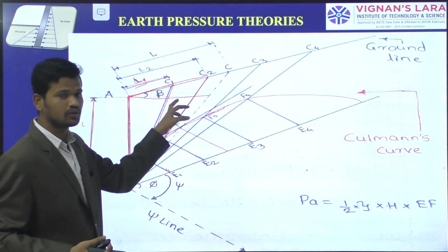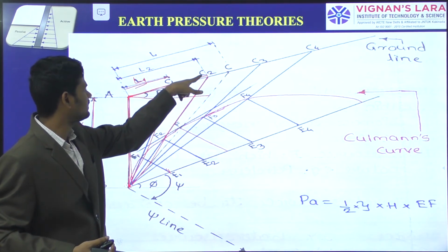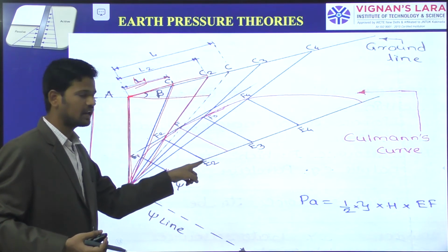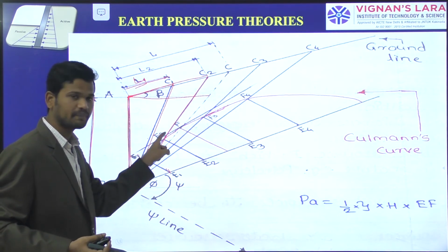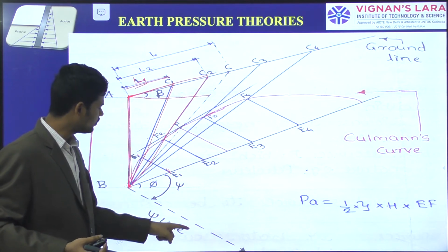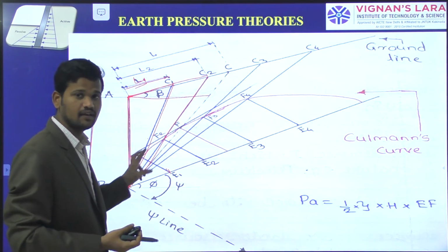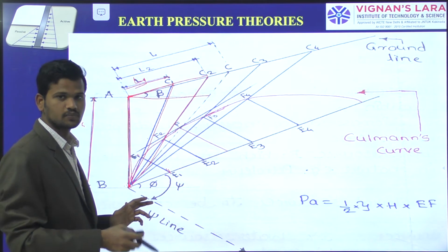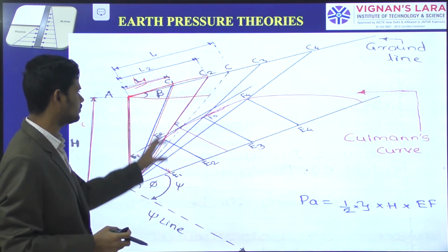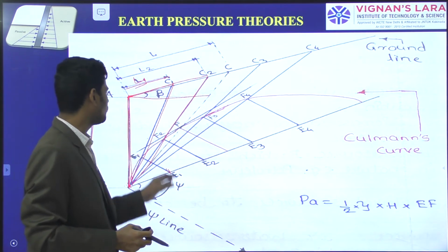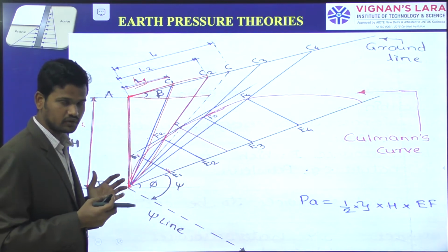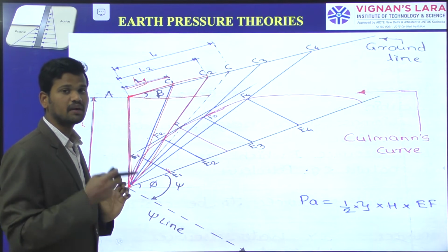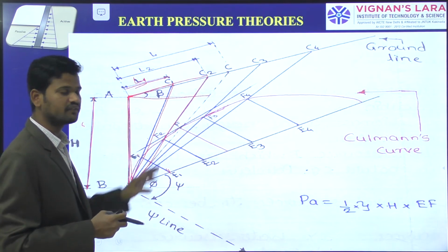After that the second triangle we are taking, and again for the second triangle AC2 length, how much it is, we are representing one more point here. For this point corresponding to that particular failure of the soil wedge, with respect to the J line, parallelly we are drawing the corresponding lines such that we are connecting different points, that is E2, E3, E4. However many trial wedges you are taking, that many failure planes we are drawing for the